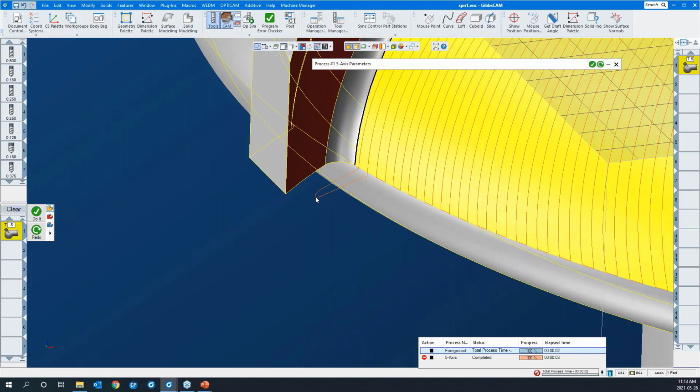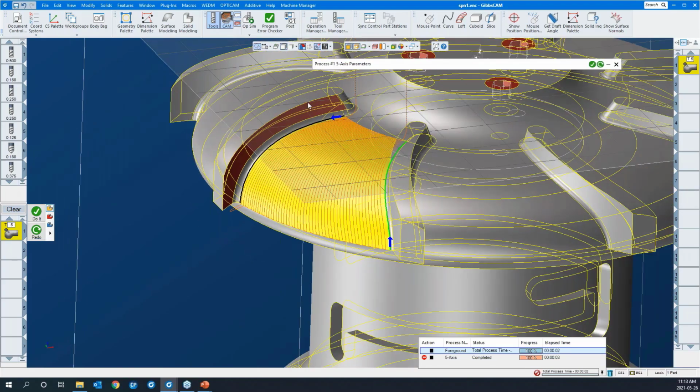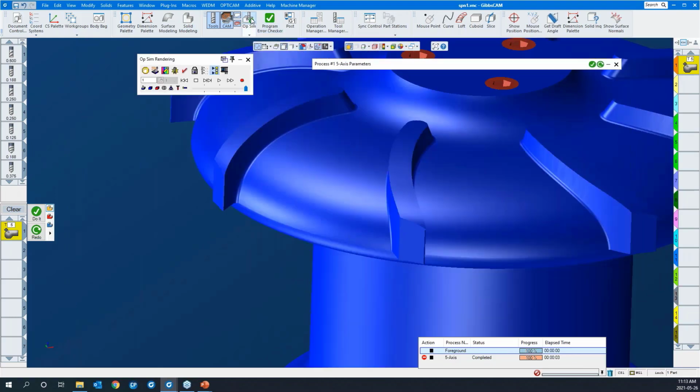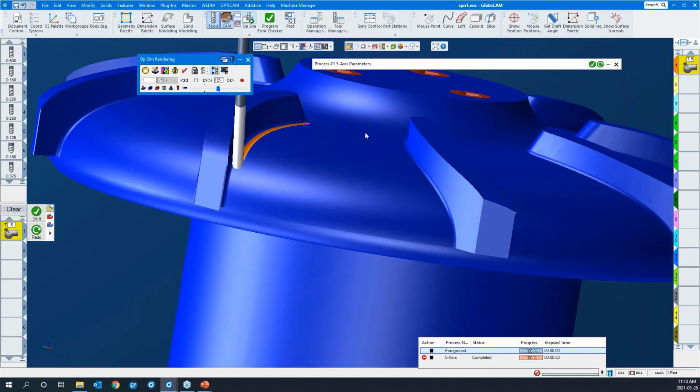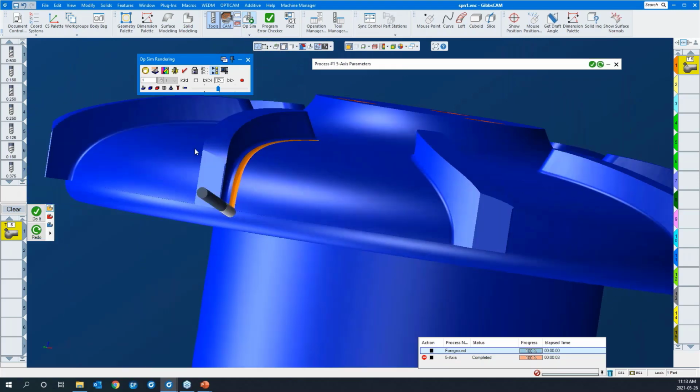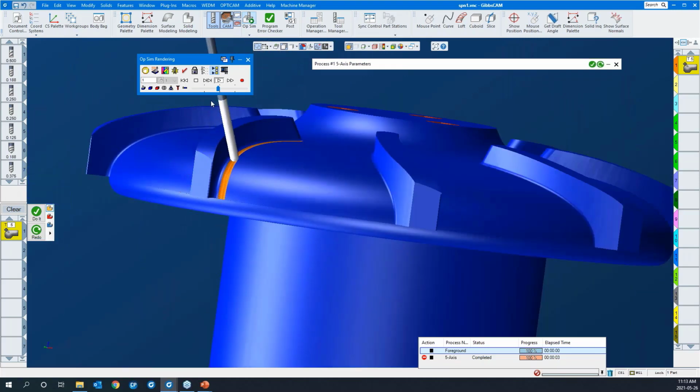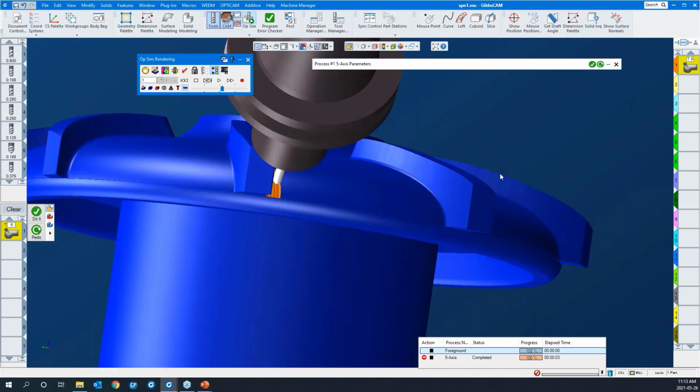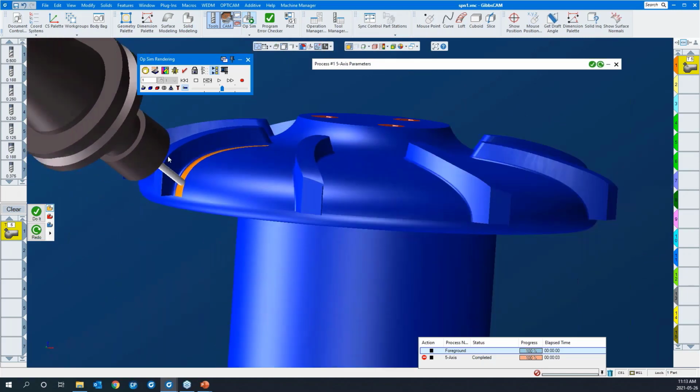And you can see there's a little jog in the toolpath, and let's look at the simulation. See how that behaves. I'll slow it down a little bit, hit play. So it comes down and you can see the tool is actually missing there. Okay, while it's running simulation, you can single block it at any given time. You can put the tool holder on there as well.